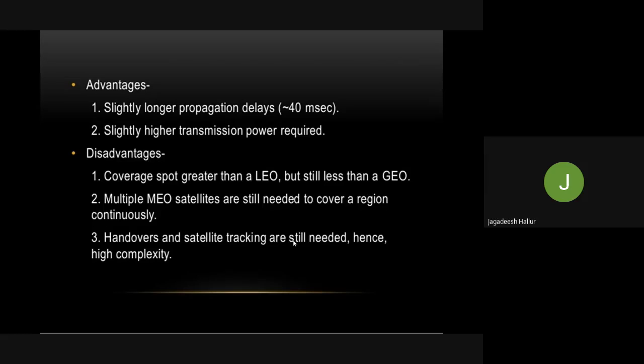Handover is nothing but what? In mobile communication, when the user is moving from one base station to another base station, you are going to change the channels, you are going to change the frequency band, you are changing the base station. That is called handover.